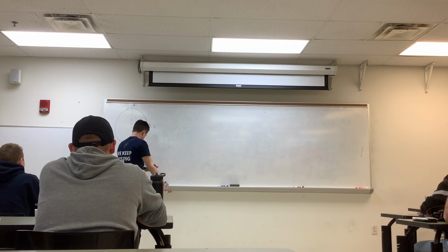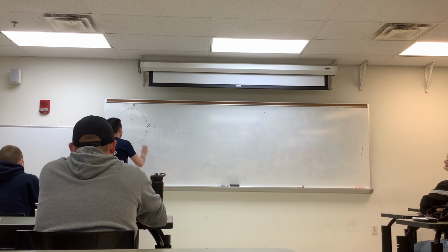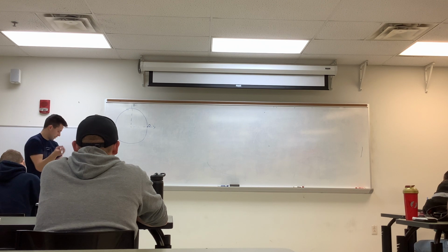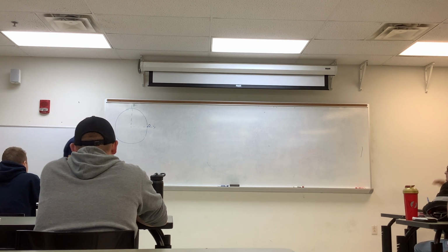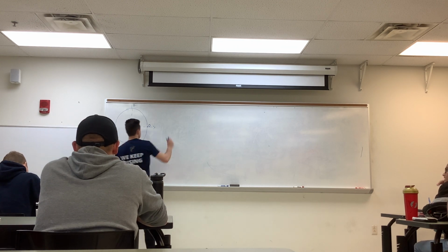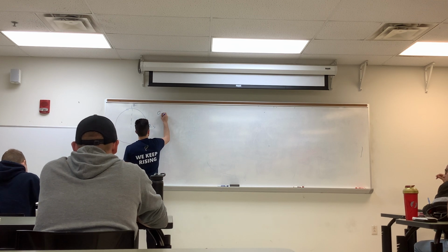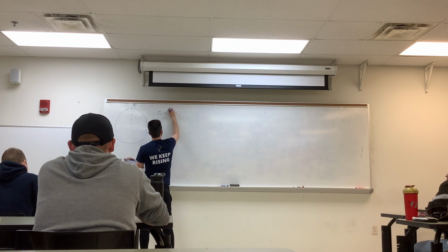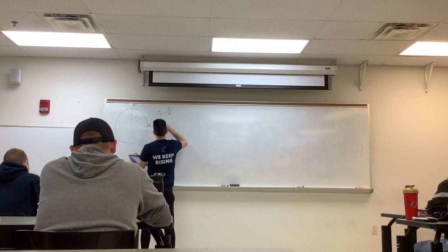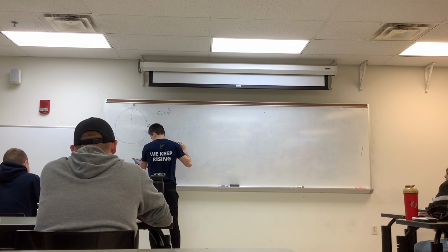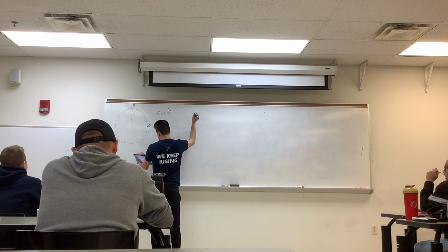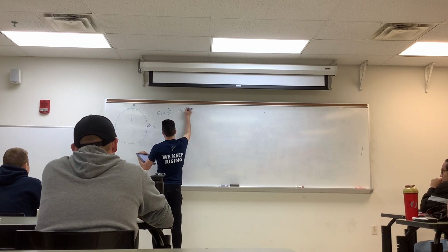Similarly, in this case, we had our force in the x, or our axial force, and then our two corresponding moments, the moment in y and z. So our equation is sigma x, the side of the plane, equal to our force in the x over A. Then we also have our M sub y.